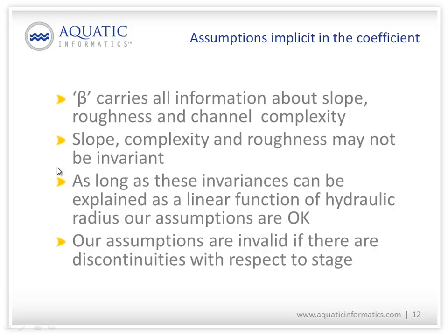Similarly, if we're looking at cross-sectional information, we may see from our field observations that the channel configuration changes at a certain stage, and we would expect the curve to shift to the right or the left above that breakpoint. So we would introduce a breakpoint into our rating curve to accommodate that point of change in the channel geometry. This gives us a lot of power to connect our field observations to our analysis in the Rating Development Toolbox.